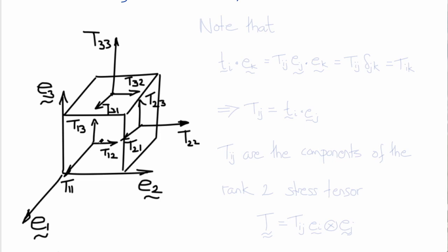And when we resolve them into their components, you see there are tangent components and normal components on the surface for each of those three traction vectors, giving a total of 9 quantities, which are the 9 components of the Cauchy stress tensor. You can see that in each case, the component pointing outward normal to the surface is the diagonal component. So T11 is the component of the traction acting on the face normal to e1 that is also normal to e1. Then T12 and T13 are the two in-plane or shear components of the stress in that plane.